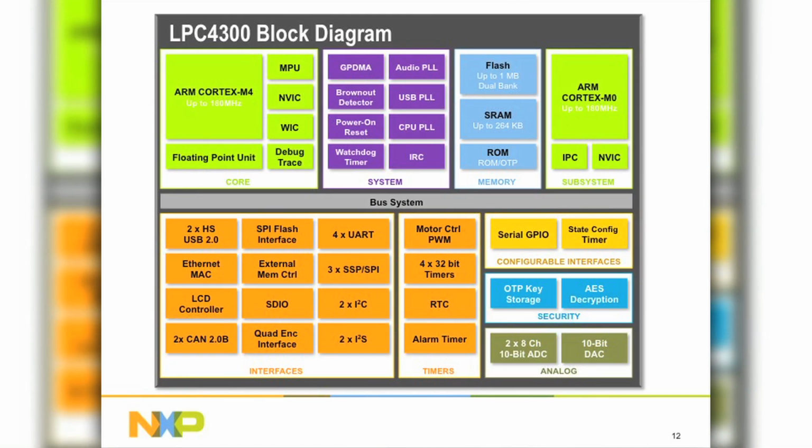A block diagram view. Here you see the dual core. The neon green color, if you will, that's ARM IP. So that's what we license from ARM. That's going to be the same no matter which competitor it happens to be. Although some of those, like the memory protection unit and the floating point unit, are optional, meaning the licensee may or may not have included them. High performance M4s almost always have the floating point unit, but it's worth checking if that's of interest to you, because not every M4 from the competition has the floating point unit.